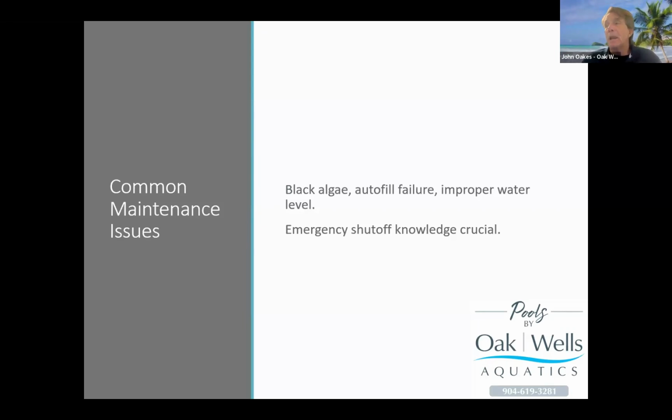And what happens when you brush the pool is that those spores that I mentioned earlier that may have fallen into the water and settled on horizontal surfaces get brushed up off of it and drawn into the filtration system and eliminated from the pool. If that doesn't happen, if they're not brushed up, they'll start to blossom into black algae.